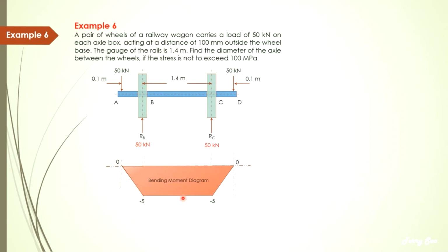So this will be the bending moment diagram, not the maximum. Maximum bending is here. Even though it's shown as -5 by magnitude, value-wise, compare 0 and 5. So 5 will be maximum. You just omit the sign, unless you have positive and negative signs, then only you start comparing. So based on the bending moment diagram which I have drawn, the maximum bending moment will